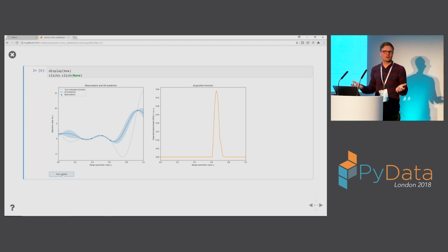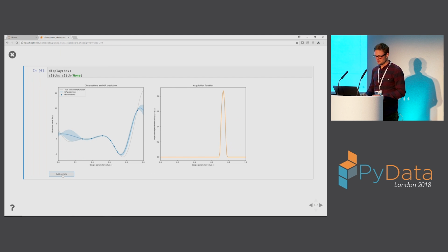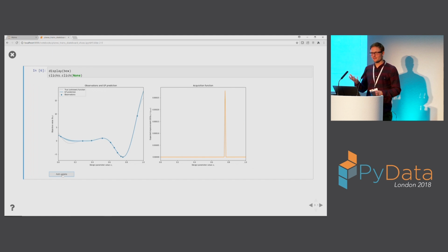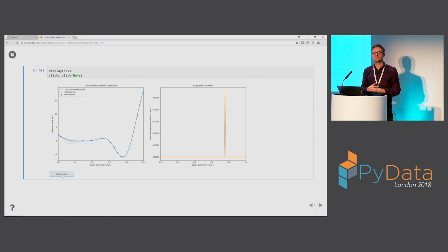And that just took another 4 hours. So what do I do next? I just sequentially iterate and keep maximizing this area of expected improvement and then adding and running a new design there. So after about 10 evaluations, I've found this minima, so I've minimized the drag of this design. That's still 40 hours worth of work, so even though there are very few data points, it's still an expensive, time-consuming process.